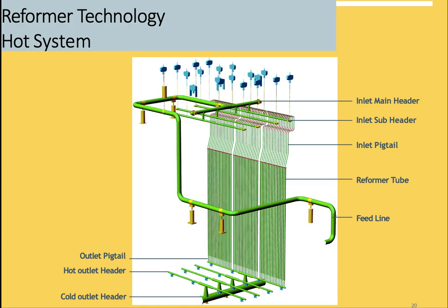Corrective action is to adjust the air to fuel ratio, clean the burner, or readjust the burner on, burner off, which is critical. In some cases it's implemented by vendors here, burner off, burner on, related to the capacity. Balanced draft control and verify at the stack the O2 concentration to solve this problem, which is flame instability.